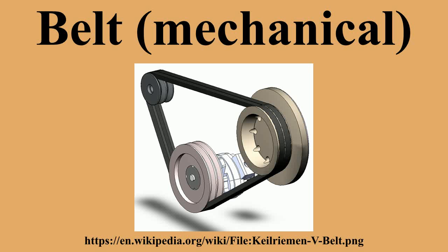Belt replacement is an obvious solution, and eventually the mandatory one. Often, though, before the replacement option is executed, retensioning may be successful to extend the belt's lifespan and postpone replacement. Belt dressings are typically liquids that are poured, brushed, dripped, or sprayed onto the belt surface and allowed to spread around. They are meant to recondition the belt's driving surfaces and increase friction between the belt and the pulleys.